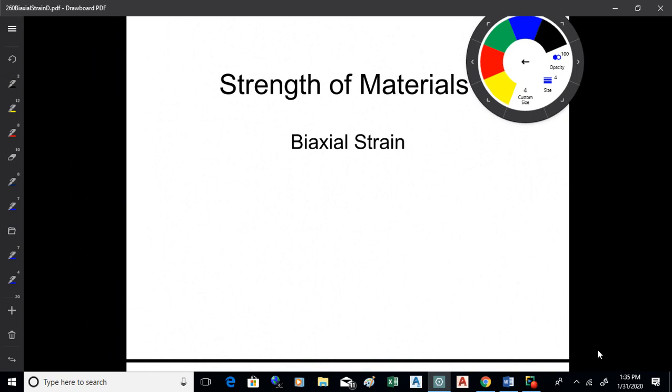So this is on page 470. It's these involved equations. I had to set them sideways on your page to fit them in. It's like biaxial stress, but it's for strain. It's the same idea. So let's look at the forest before we get too deep into the trees. The idea is just like with biaxial stress: if you know what the strain is going to be in the x and y directions, you can predict what the strain will be at any angle you're interested in. That's the big picture on this, okay?